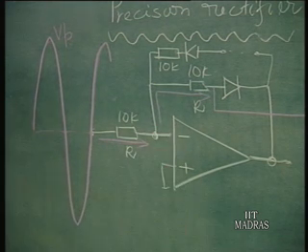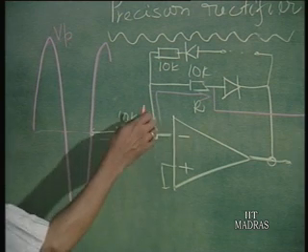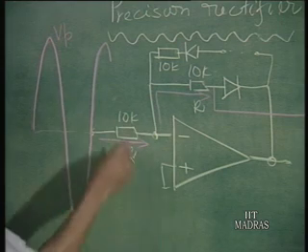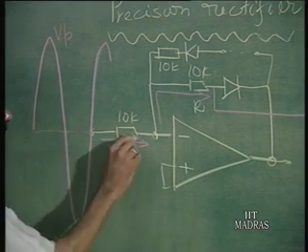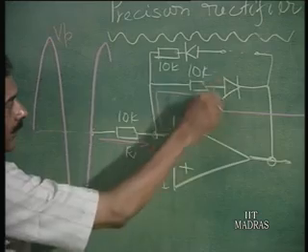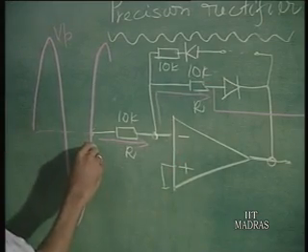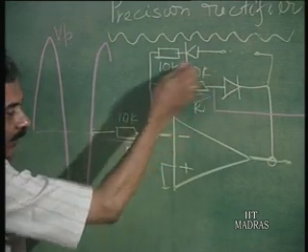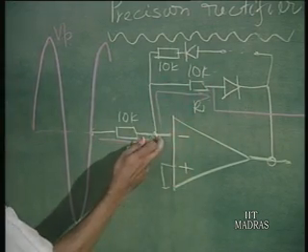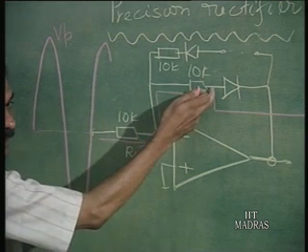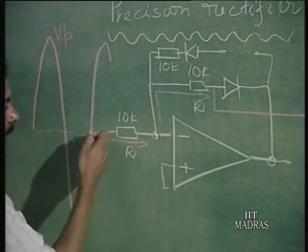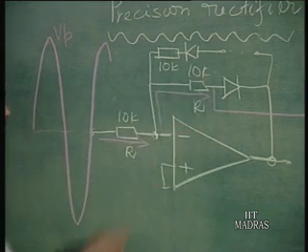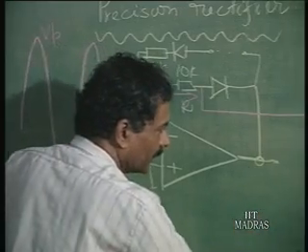So, the op amp is going to behave like a comparator there, where it will be simply magnifying whatever voltage is appearing here at this point, but that is of no use, because this positive voltage is going to get converted into negative here, and this diode is going to conduct. But when it goes negative, this is going to be having open loop. If you do not have this conducting, this will be open loop, and this voltage will appear here, and this voltage will appear here as well. So, when it goes negative, the input voltage will appear here. When it goes positive, this is going to be inverted. Therefore, with the resultant effect, you see a waveform like this.